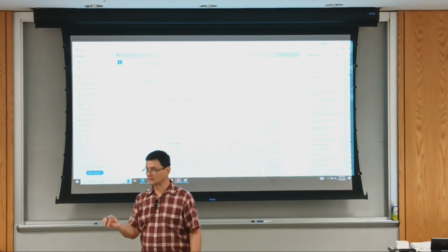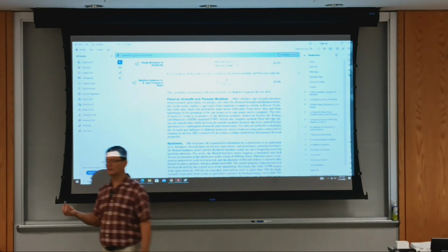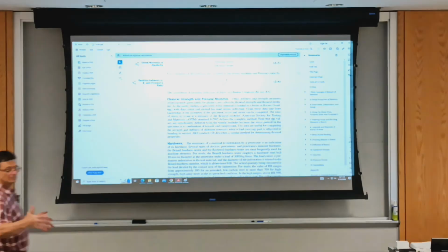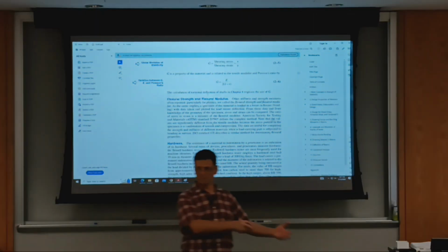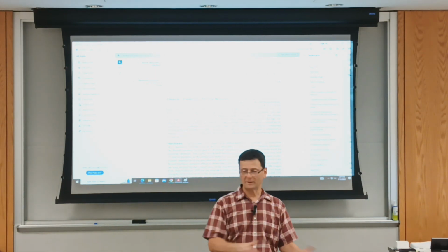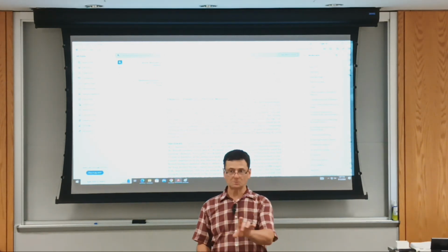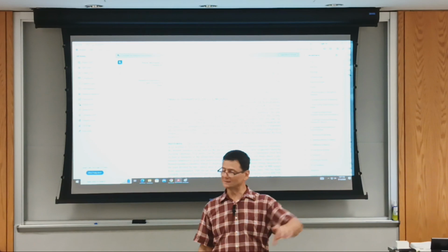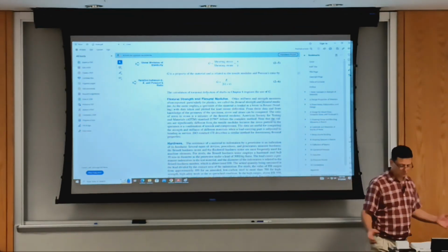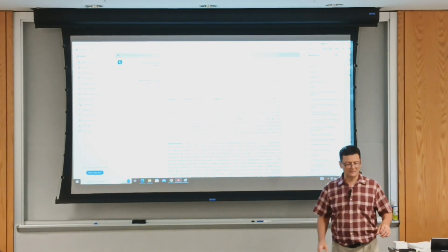You can see it. You can even see if you take apart maybe a transmission, because they do random or process control, and they take a gear and put it on a hardness tester, look at the numbers, and may reject the whole batch. Or you may see them say, oh, that's perfectly fine. It just has a little dent, and it ends up in use. Of course, you can't say the same with tensile testing.